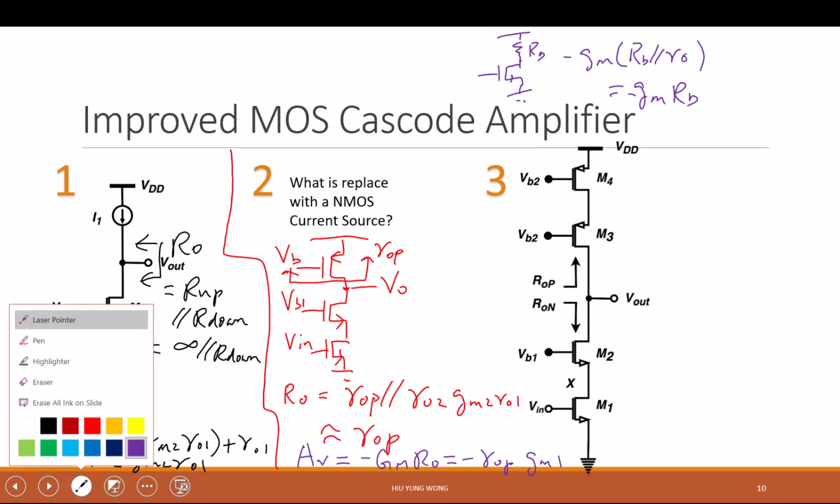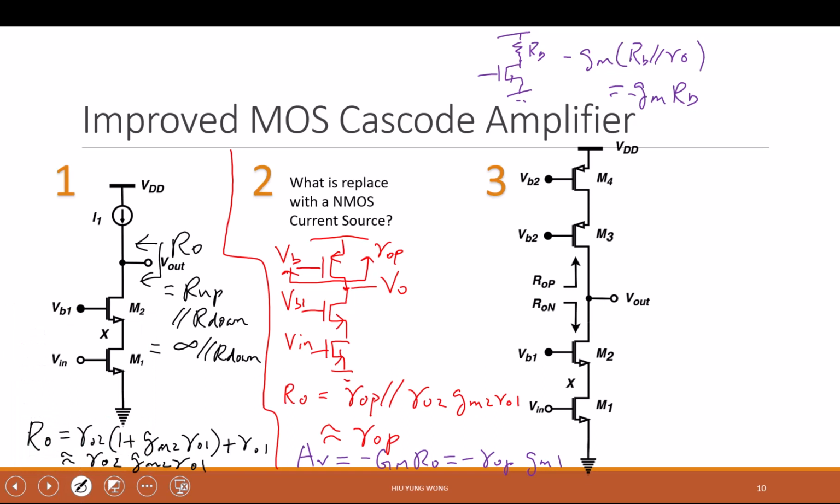Okay. So if that is the case, how do we solve the problem? It's nothing difficult. It's just that for the loading, let me use the cascode also, right? So on top, if you look at the bottom first, this is drain, this is source, this is drain, this is source. Looking up, this is drain, this is source, this is drain, this is source. Again, it is cascode, right? Because we're going to ground it, this is a constant voltage. So naturally, R up is just the same. You still have RO3, GM3, RO4, right? I use the simplified one, okay?